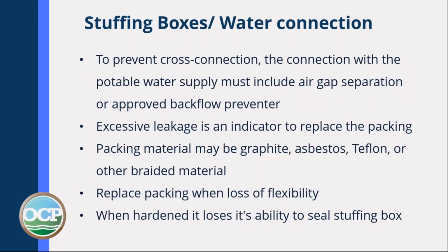The stuffing box is a water connection, since it uses water as the lubricant. To prevent a cross connection, the connection with the potable water supply line must include an air gap separation or an approved backflow preventer. Nobody wants wastewater in their drinking water.